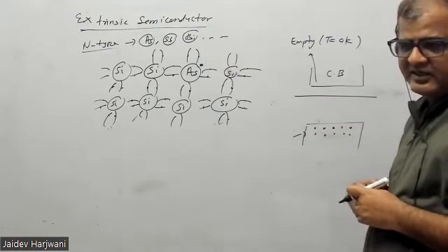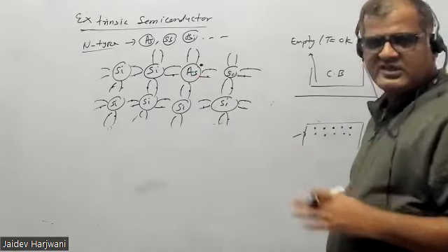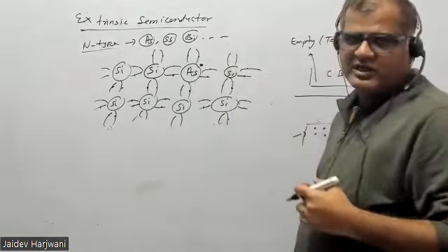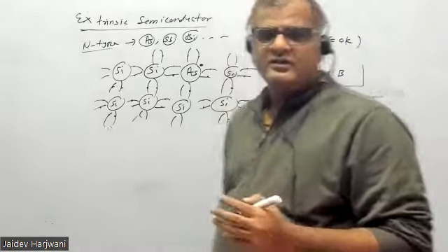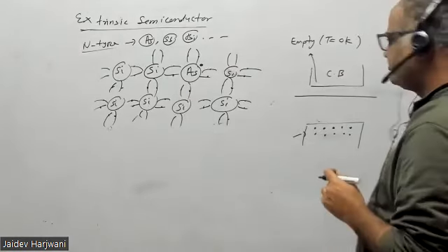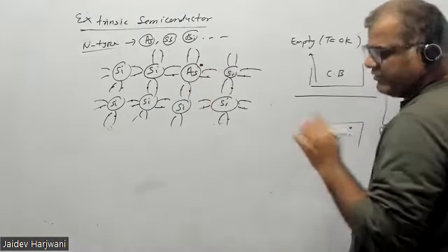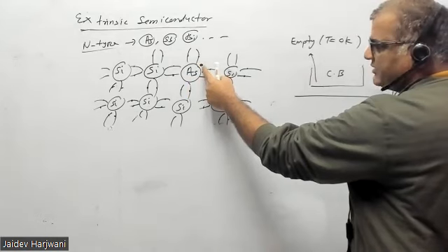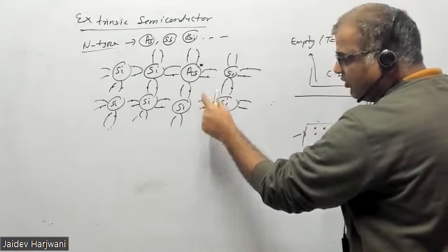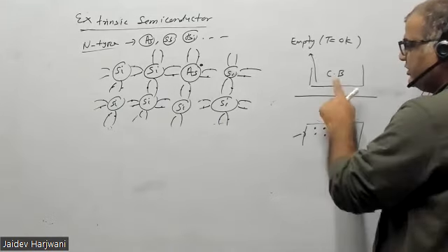If I want to ionize arsenic, because this is a neutral atom, if silicon is neutral and you are adding arsenic, which is also neutral, so if I want to remove the outermost electron of arsenic, then this atom will become arsenic plus. The energy required to make it free means I have to send this electron to the conduction band. If it were covalently bonded, I would have to take the electron to the valence band, and from the valence band it would come here.